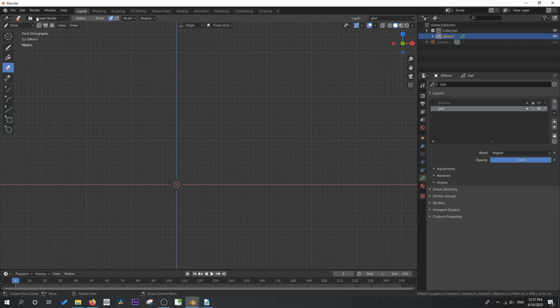We'll go over into draw mode, and using our draw ink set to gray line, I'm going to enable the line primitive, click, and holding down Shift, I'm going to drag to draw a line roughly at the 0 mark, again at the 1 meter, again at the 2 meter, and then in between at the sort of 0.5 meter mark.